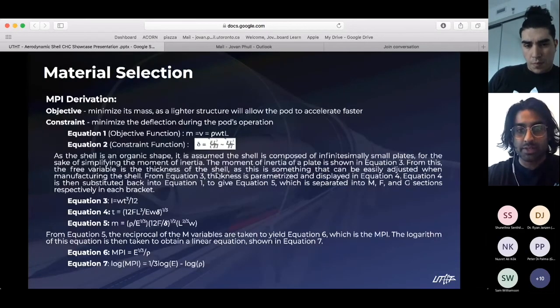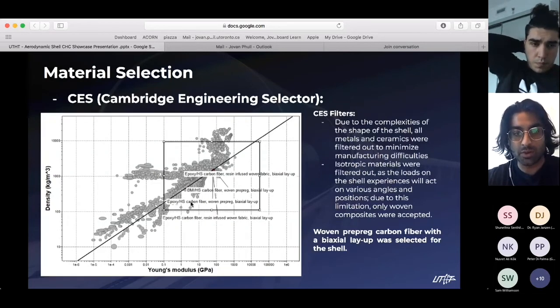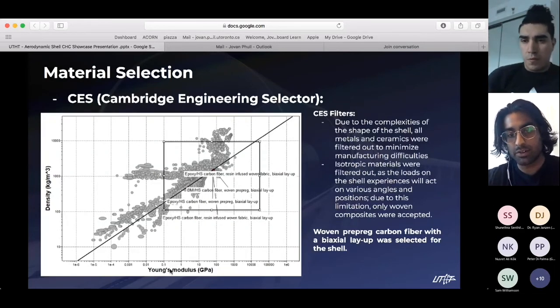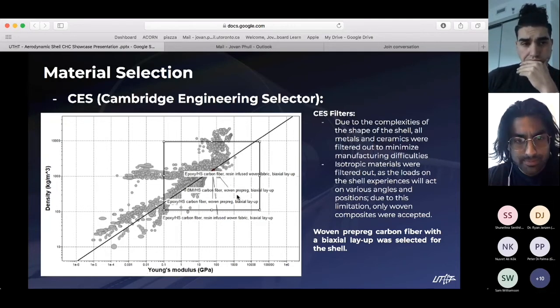If we incorporate something with the honeycomb structure in here, essentially what we're doing is lowering the density. Although our stiffness or Young's modulus might be decreased, we're lowering the density such that that material will lie on the right side of the line. I don't know if that answers your question. I can try to give a better explanation if you need.